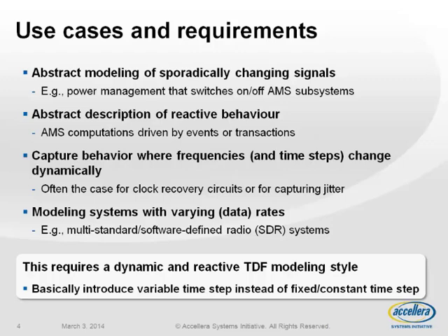The possibility to be able to capture behavior where the frequencies and thus associated time steps change dynamically, which is very often the case when you have to deal with clock recovery circuits and to be able to capture jitter, for example, in your clocks, in your sampling clocks, or also when you're dealing with PLLs and other systems and radios where the phase or frequency is modulated.